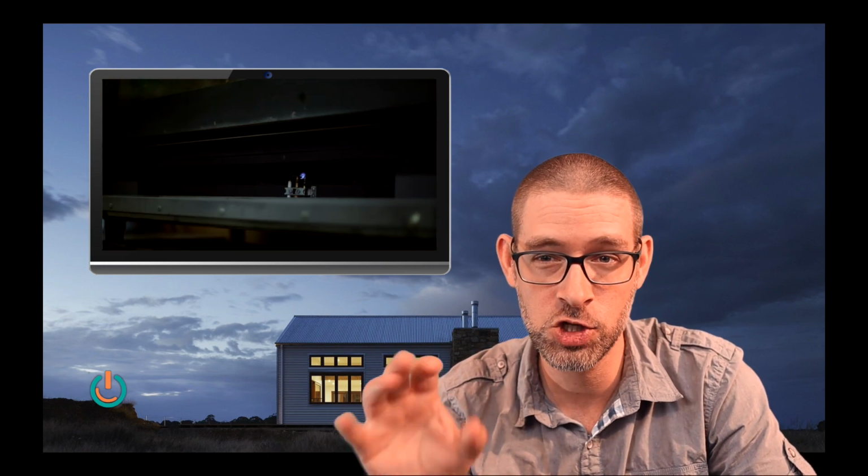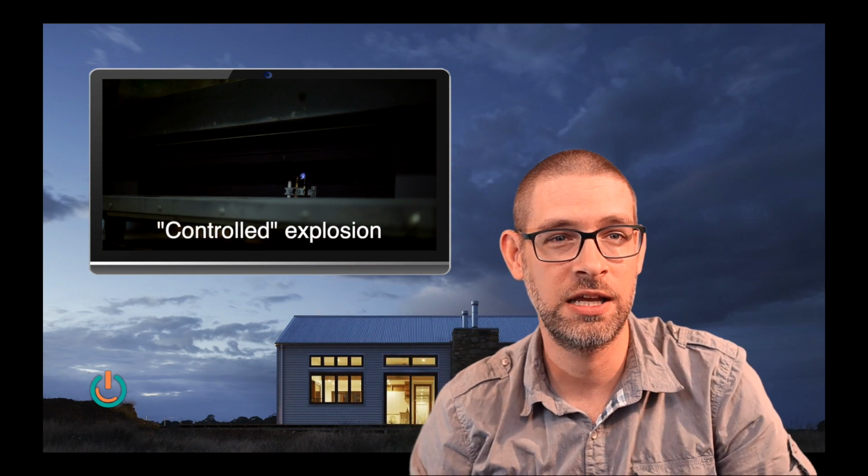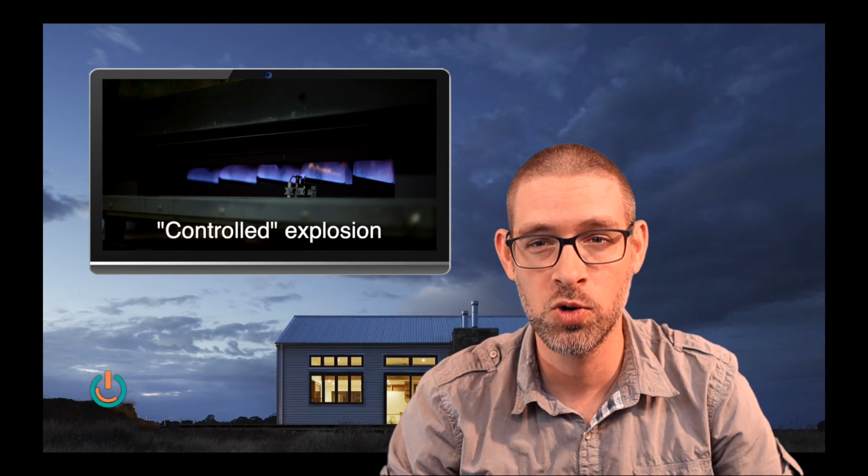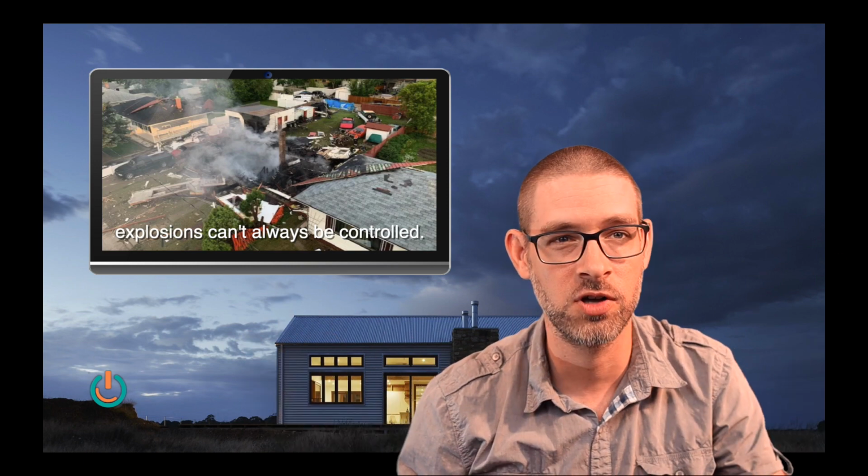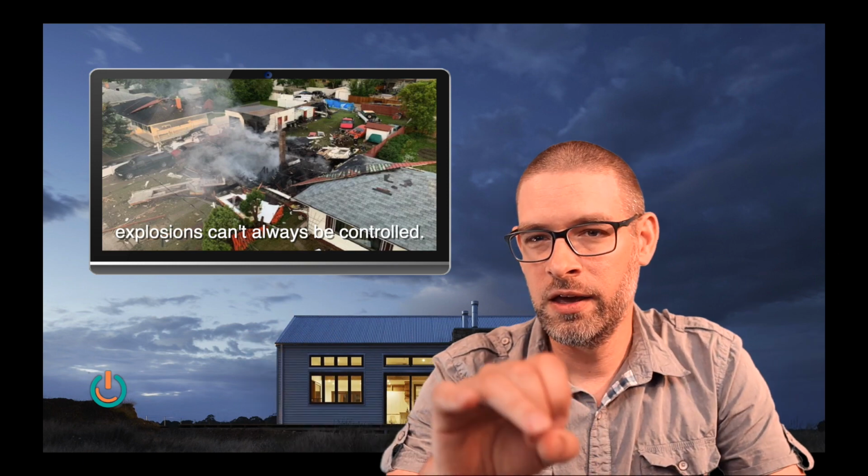Well, not with a match. We actually use a little igniter in the furnace that shoots an electric charge into a gas chamber where it explodes, and then we get heat out. We bring a controlled explosion into your house to heat your house with fossil fuels. That is what we do. And there are some byproducts of that combustion process, like carbon dioxide, carbon monoxide, sulfur dioxide, water, nitrous oxide. Along with that goes heat, because no combustion process is 100% efficient. It's impossible. Those byproducts, along with heat, we vent out into the atmosphere.